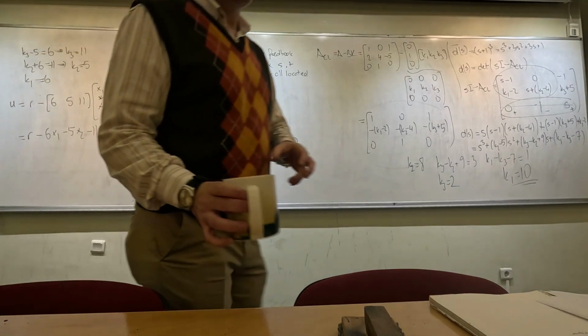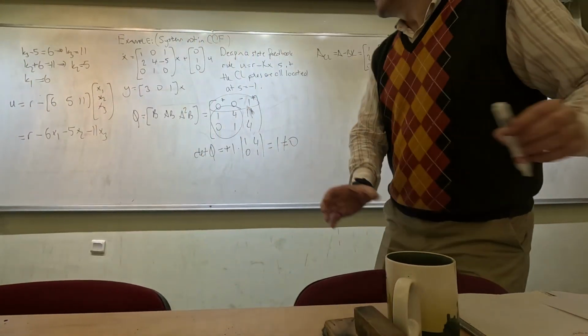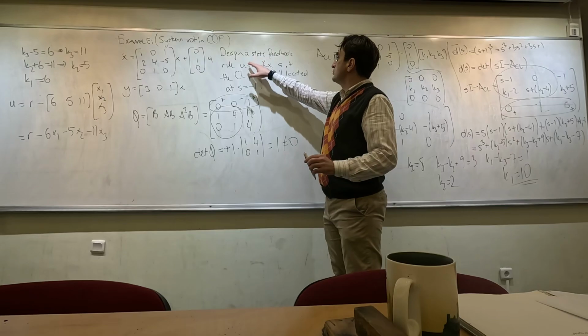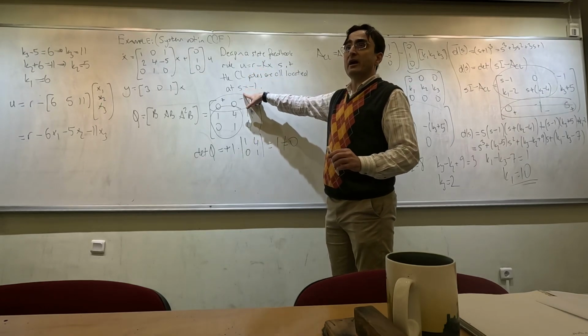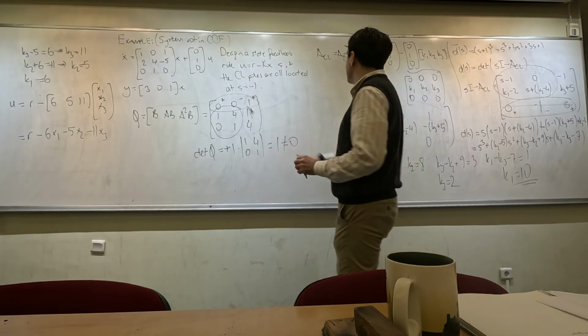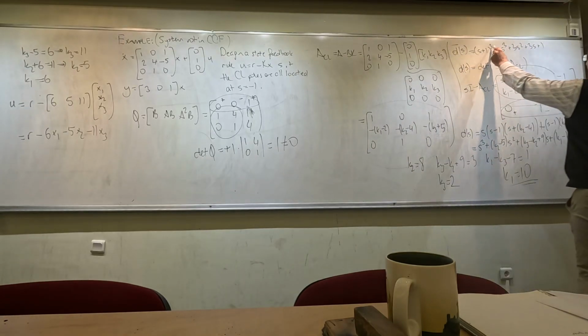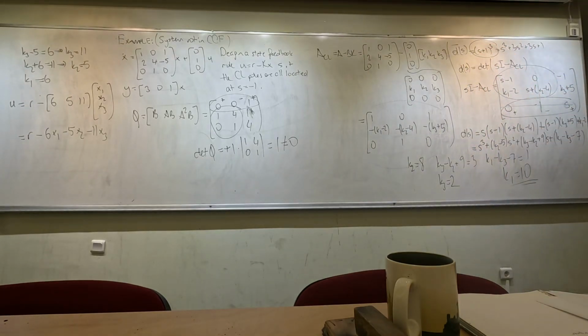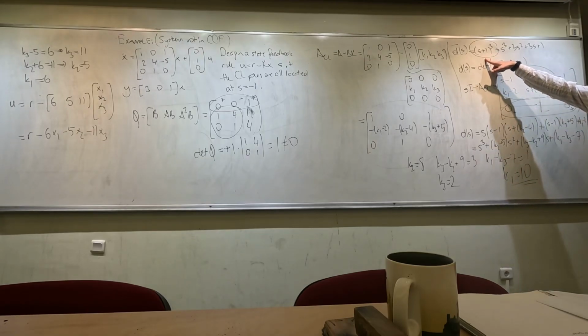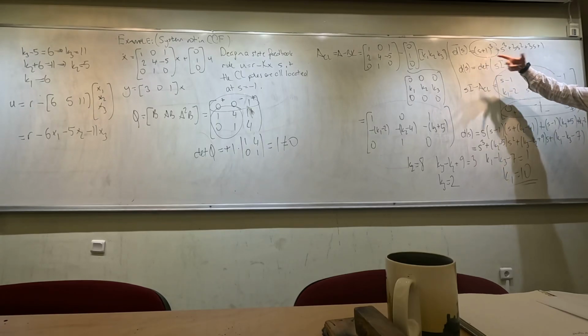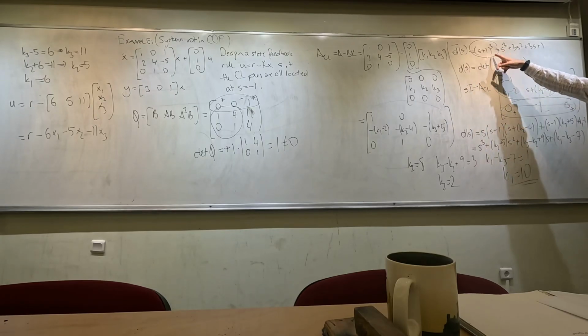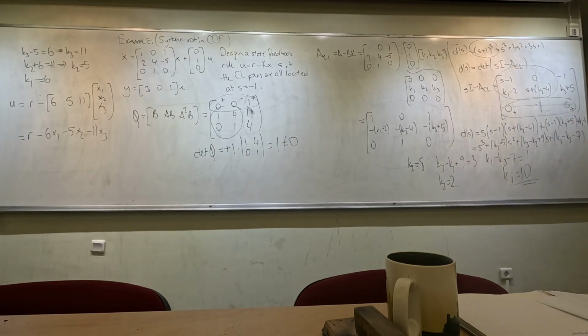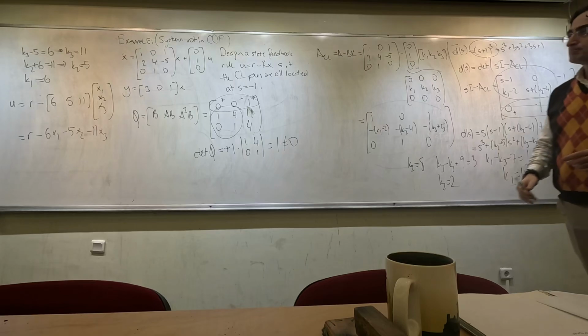That is the desired polynomial. So here, in the question, we need to place the closed loop poles at s equals minus 1. Okay? So here, this desired characteristic polynomial would determine that. If I equate this thing to 0, then all of the characteristic polynomial roots will be at minus 1. Okay? And that is why I choose my characteristic polynomial to be equal to (s plus 1) cubed.